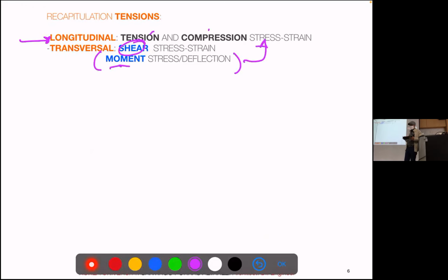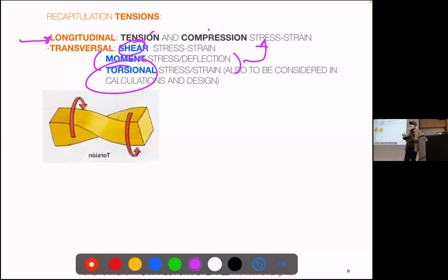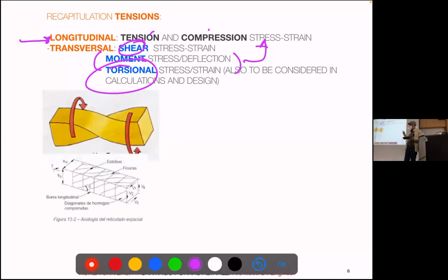This is what happens, right? And the effect will be similar to shear stress. So you will have diagonal cracks. If you imagine how it forms, you will understand the cracks logic. And since this is rotating, all the tensions will be accumulated on the exterior, right? This is just because you have more moment.